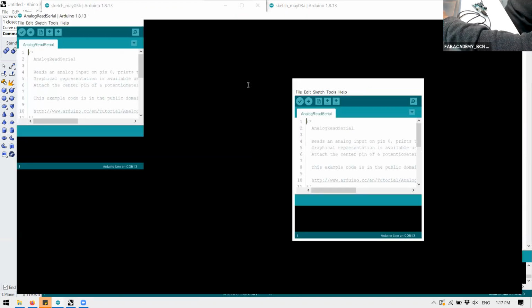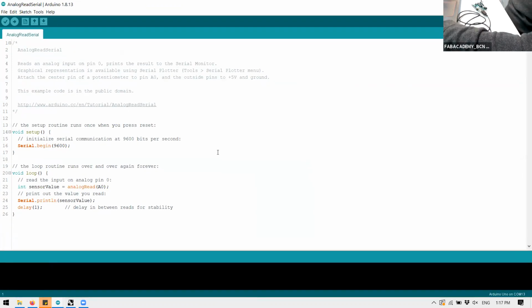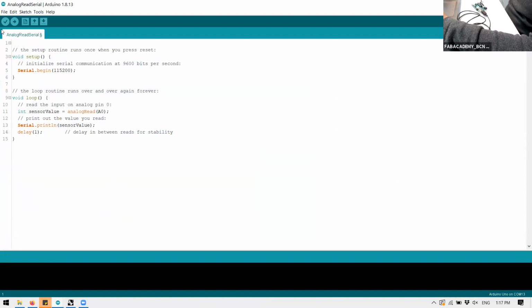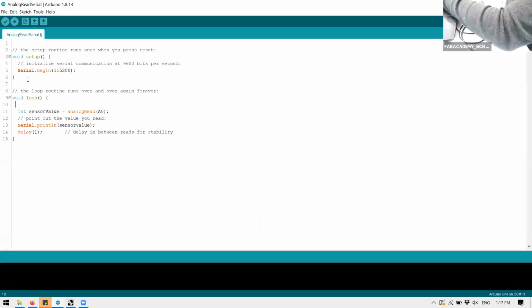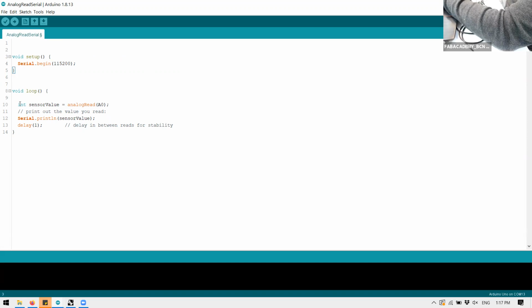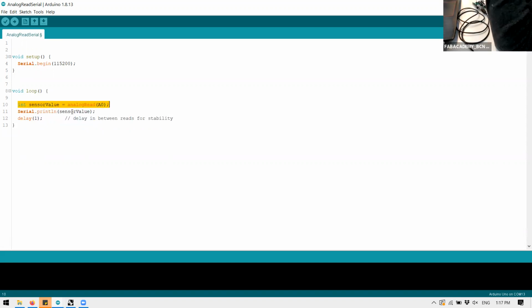Because when you read a sensor, you want to see if you are reading it. So actually you're automatically doing this. So let's change the speed of communication, so we match the Firefly one. Okay. Let's take out the little piece of quotations that we don't need. We are reading analog 0 and we serial print the value. Let's read just one of the joysticks. Okay. Click, upload.